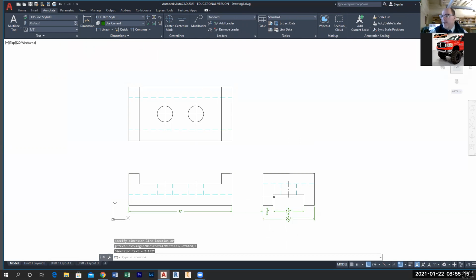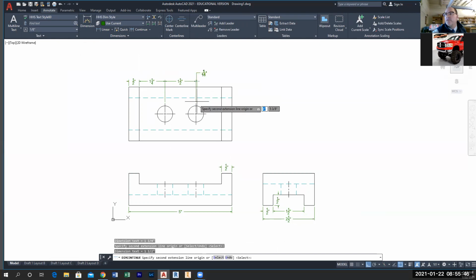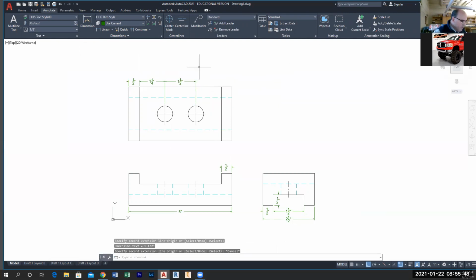All right, I got a dimension in here that's a 1/2 inch. Let me go linear again and go here and here. That's a 1/2 inch dimension there. Okay, and I'm putting all these dimensions in here. I'm looking in my book. Any dimension that's in the book needs to be on the drawing. 1/2 inch there, okay? I got 3 dimensions that go across the top here. Let me go dimension here, dimension here. I want continuous to this center line here and continuous to that one right there, okay? Those 3 are in there, plus that one's in there, okay?